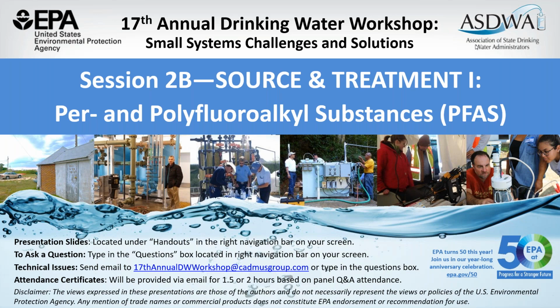So to my knowledge, there were no backwashes between change out. So obviously when there's a change out, the new carbon is put in, it's fluffed up with a backwash. That's being backwashed with treated water though, so there was no PFAS contamination in that water. So that backwashed water was just being sent to waste. I don't believe there were any backwashes after carbon change out, and I really think that's a function of there not being an extended period of time with respect to carbon contactors.